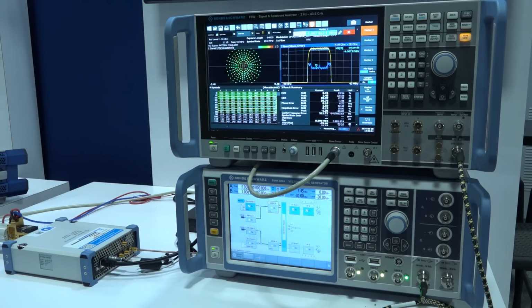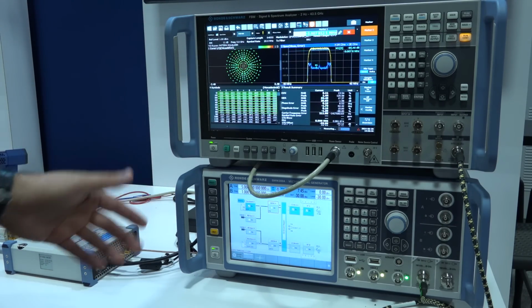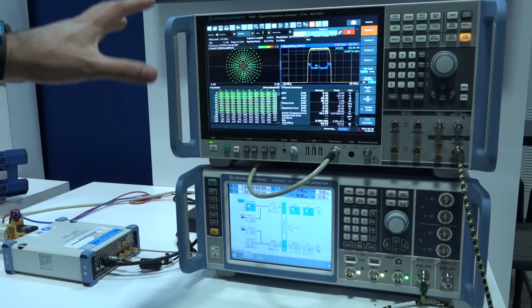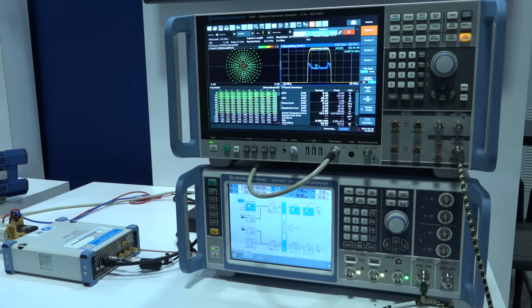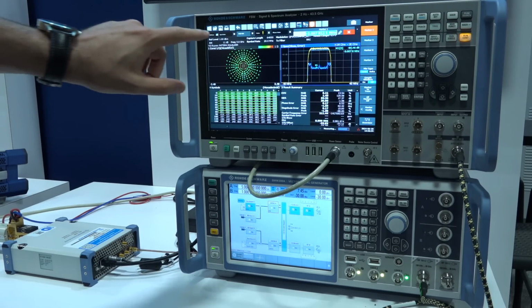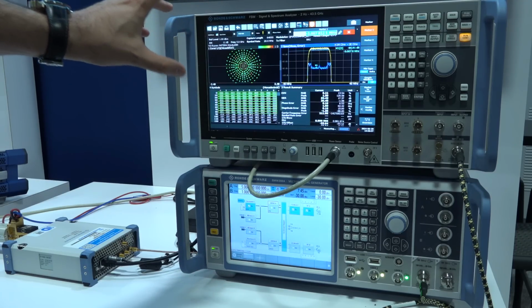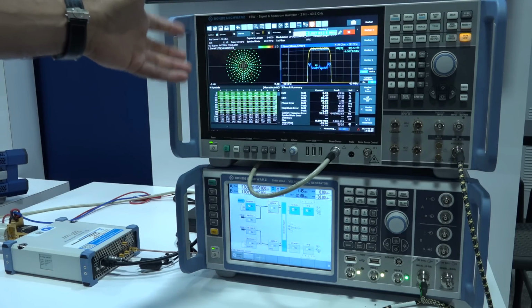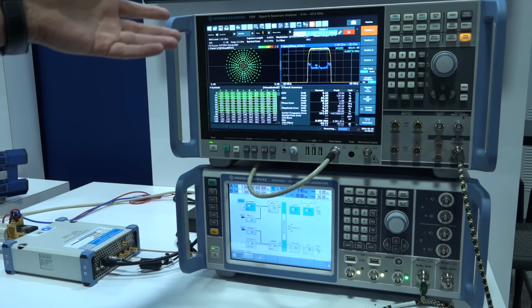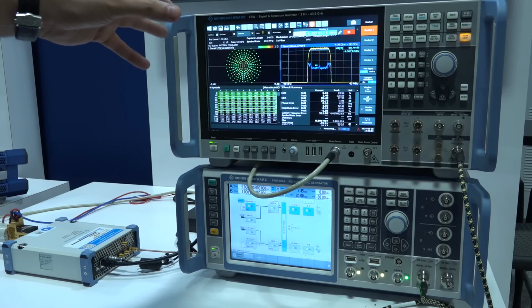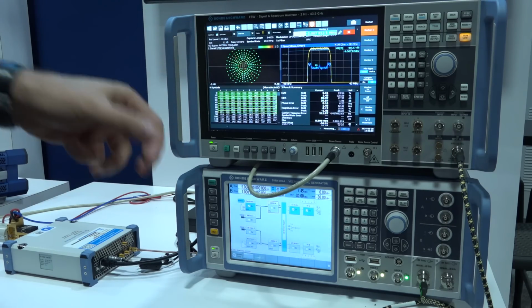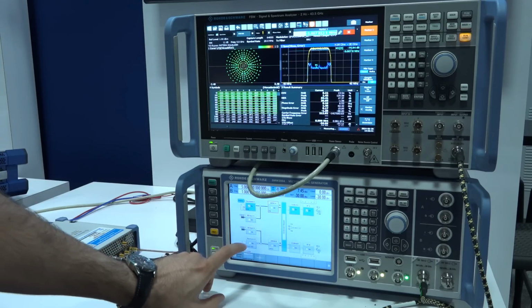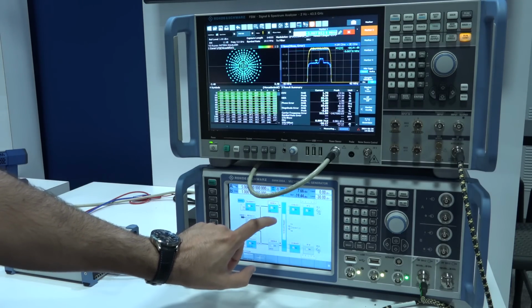So here we have the FSW combined with the SMW200A together working. We've seen this combination before, and here we're running VSE live directly on the instrument. But there is one thing here that is worth paying attention to, is that generally when you look at various constellations, the errors in the constellation typically look the same. So whether it's a wideband noise or some interference that's on the constellation, it's very difficult to tell what is causing the degradation. So what they've done as a new feature in the VSE is that if you have some unknown interference, for example, I can turn that interference on in this case,